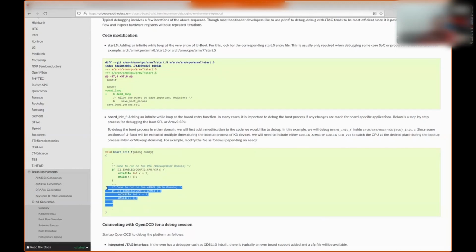There are some tricks with which you can control this by disabling the watchdog. But if you don't have the disabled watchdog trick in mind, then the only way that you can debug this is to do your entire debug within a period of 3 minutes. And we actually ran into this when we were debugging J721E U-Boot. Now for the rest of the devices, since we are using multi-certificate, ROM will automatically load TIFS firmware and the watchdog will be pet by TIFS itself.